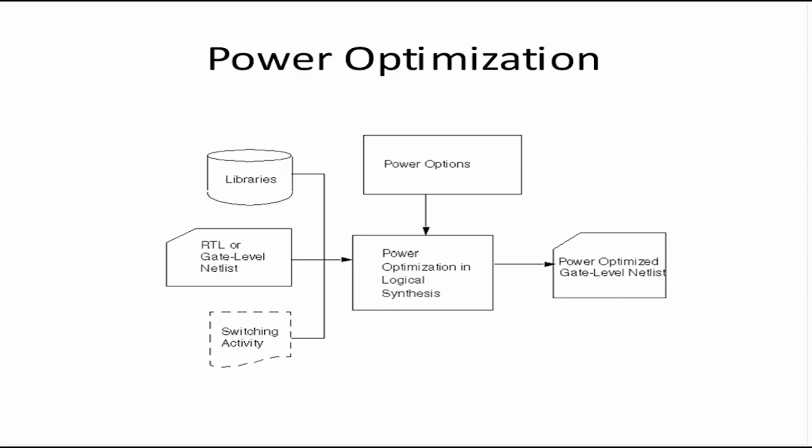Now, the last step. In this last session, we were focusing on power optimization techniques. One thing you should always do is use the clock gating option if your library supports an integrated clock gating cell. Even if your library does not support an integrated clock gating cell, you know that for any positive edge triggered logic, a good clock gating cell would be a latch plus an AND gate. Without using an integrated clock gating cell, you can tell DC, by using set_clock_gating_style,